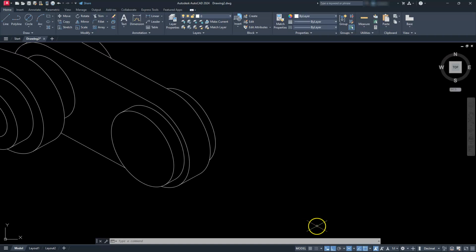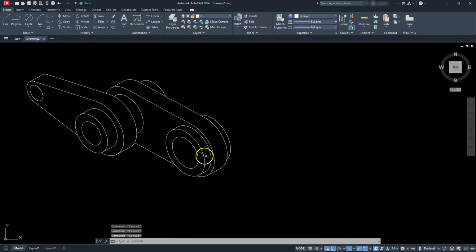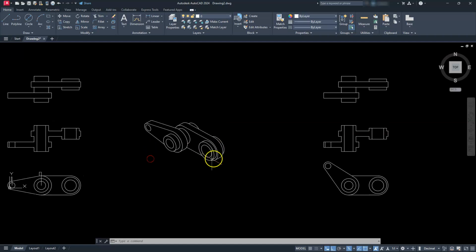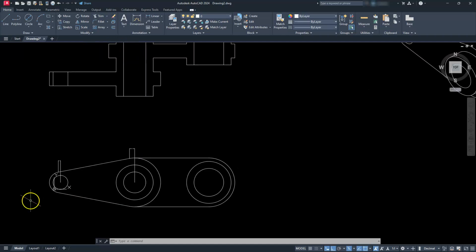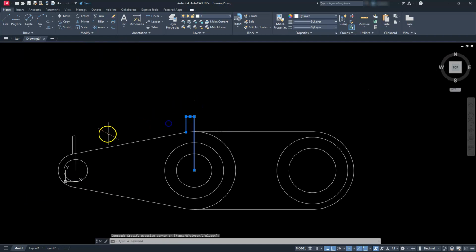All right, so let's switch back to ISO left. EL, enter, I, enter. Let's go find the center of this front one. D, enter. And this has a diameter of 40. All right. Now I can check and verify that these don't show through, and I know on all of these they don't. So there's no need to verify on that one, right? So this one takes care of associating with this view here. Let's go ahead and clean this up by deleting these extra pieces here.